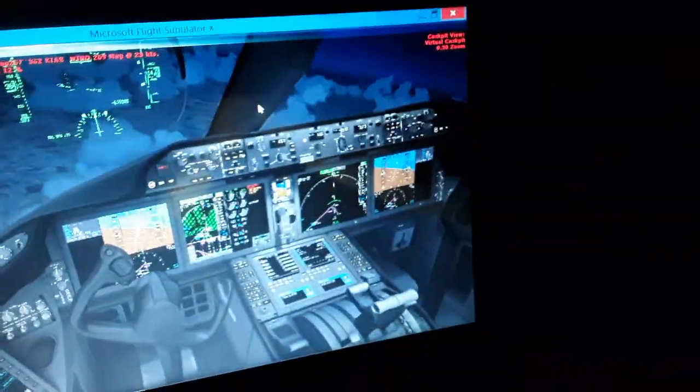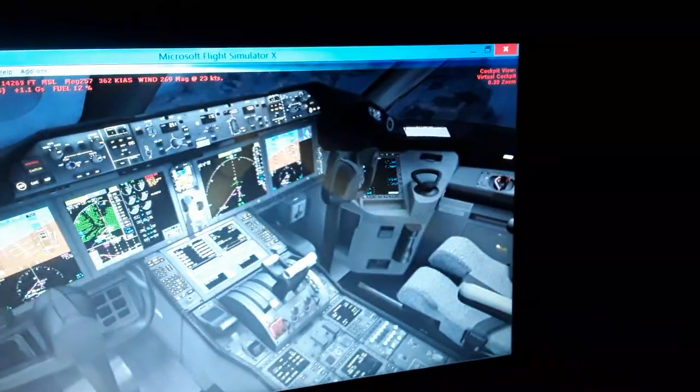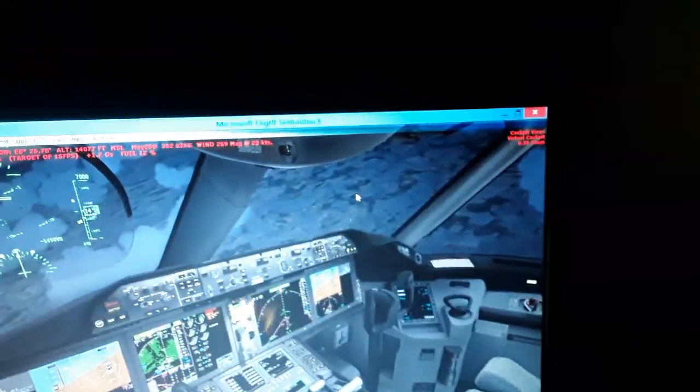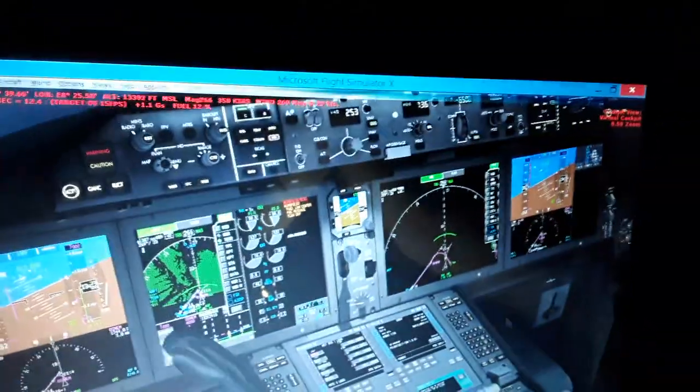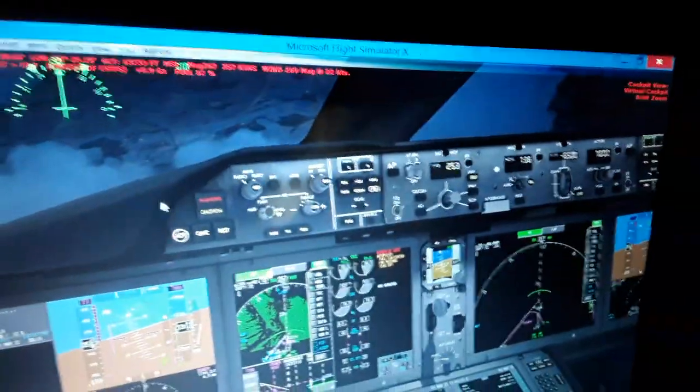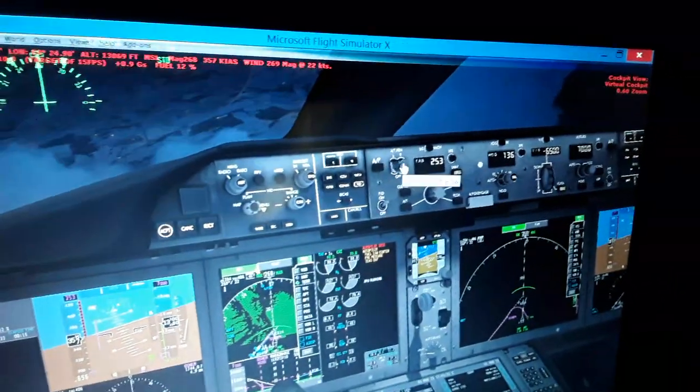So we're gonna disconnect the autopilot now like this and follow the rest of the flight plan manually as we are descending using idle thrust and speed brakes extended. You can see auto throttle left and right off, autopilot reset.